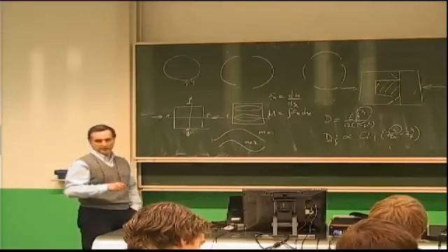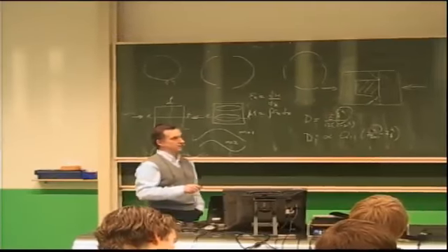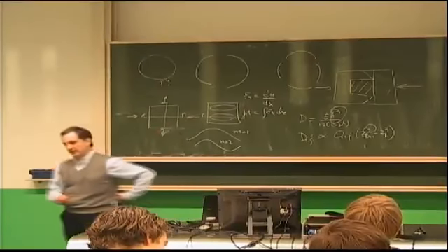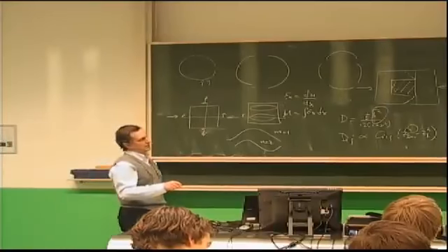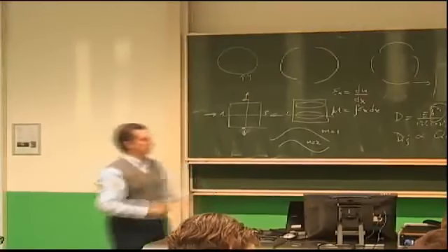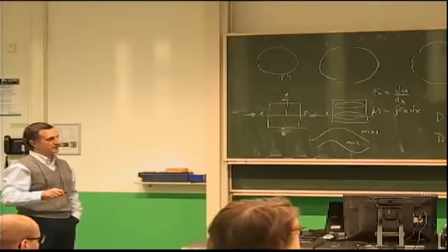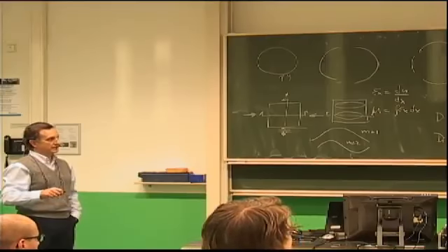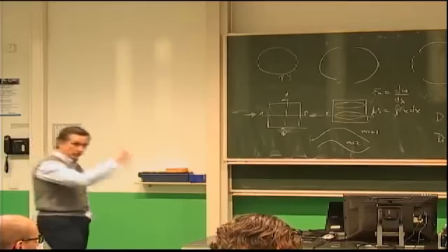If I now try to compare the weights, I have the density ratio, 0.58, that's about the density of carbon epoxy compared to aluminum, times my increase in thickness, 1.063. The width and length of the plate stays exactly the same to compare one to one. And I see that the graphite epoxy or the carbon epoxy is 61% of the aluminum, or 38% lighter. So that is very encouraging. You say, okay, composites are 38% lighter, but this is only part of the story.